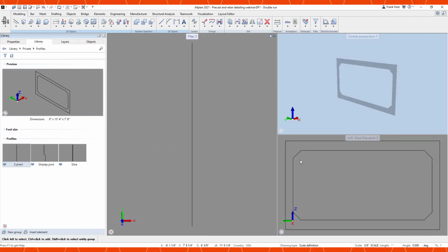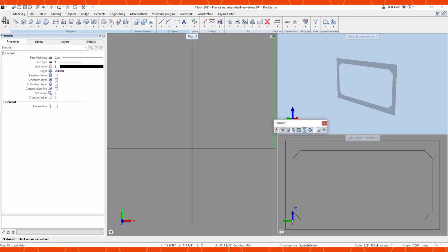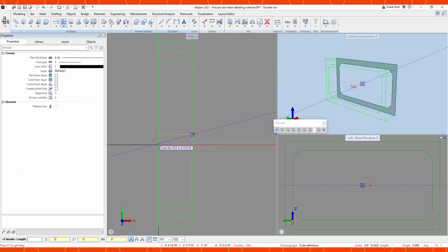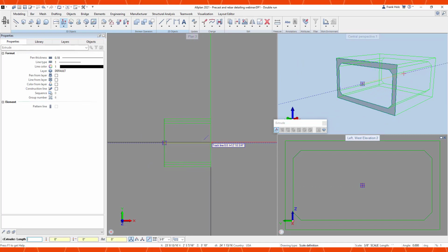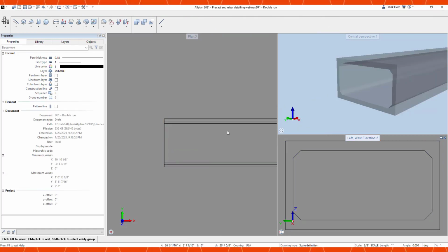As you can see, this is just like anything we draw ourselves in 2D, but I've taken it and converted it into a 3D surface and oriented it in its proper location. Now I'm going to use our extrude tool to turn this into a 3D shape. You can see if I had an overlay or an underlay, I could easily click on that and screen, but I'm just going to type 100 feet for my barrel now.